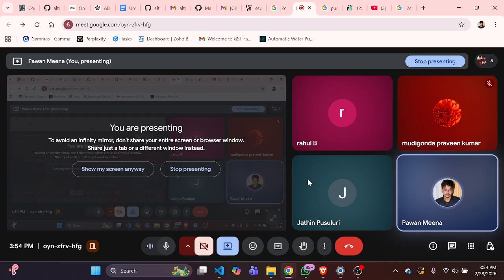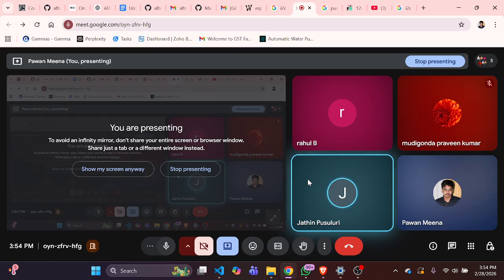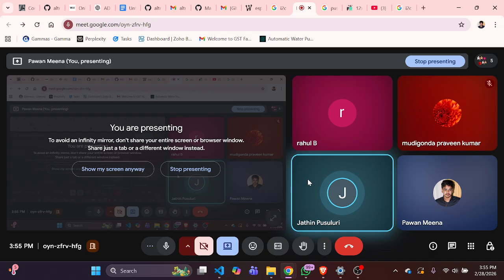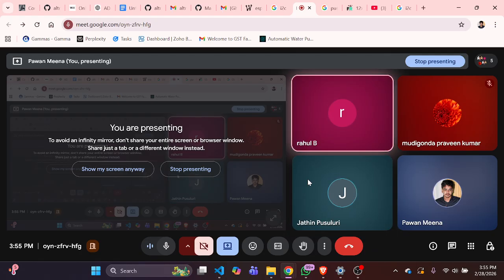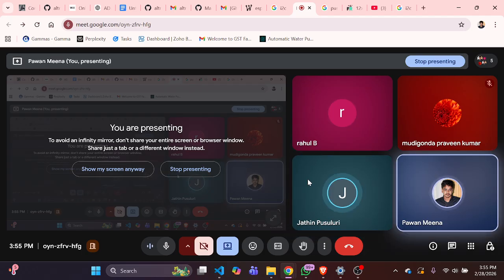Remove all the connections if it is heating. Everything was working properly, but from today, from before the relay onwards, it's getting too hot. Within 30 seconds of powering it up, it becomes too hot. Without any connection even, right? No, even without any connection. While flashing the code also, it's becoming too hot. I don't know why. I'm even unable to touch the core part, that metal part.